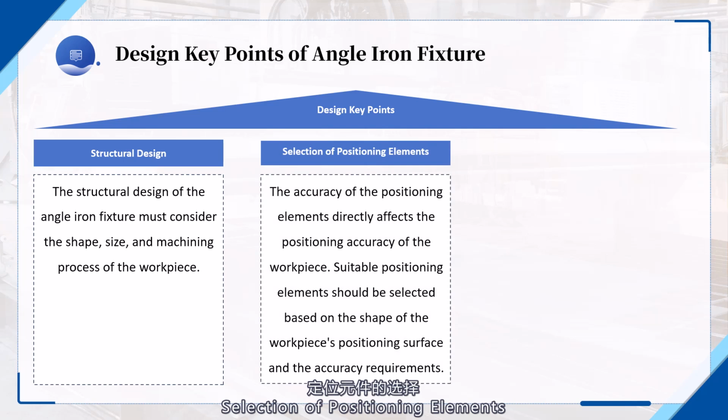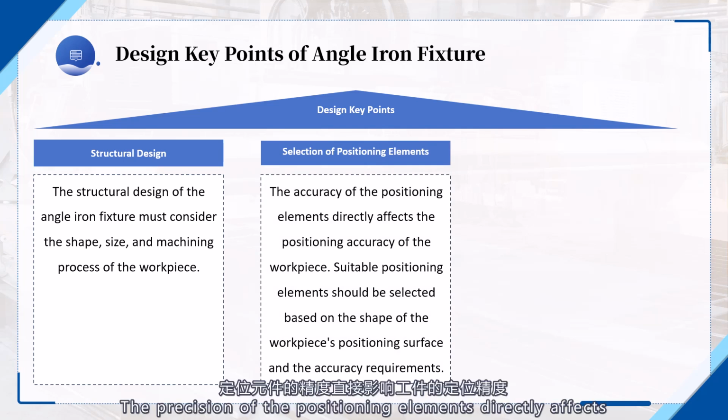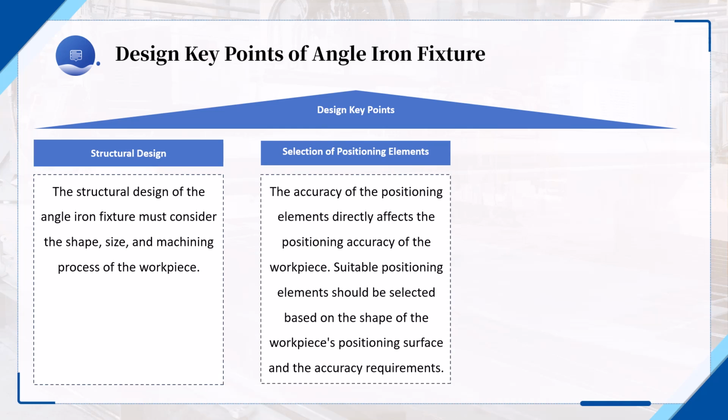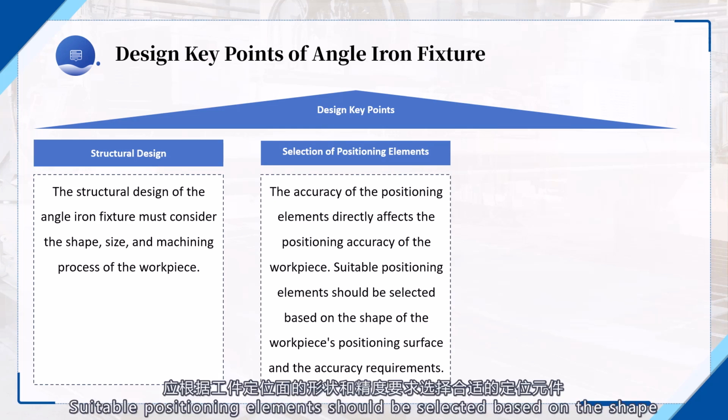Selection of positioning elements. The precision of the positioning elements directly affects the positioning accuracy of the workpiece. Suitable positioning elements should be selected based on the shape of the workpiece's positioning surface and the precision requirements.